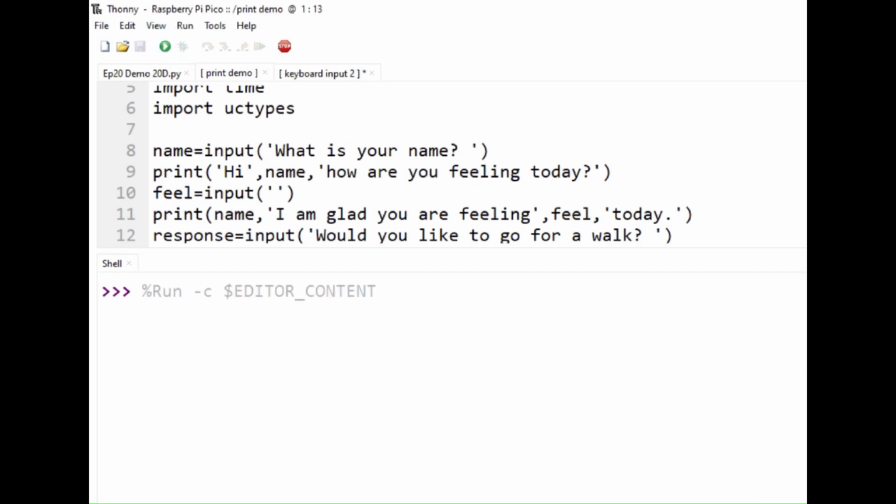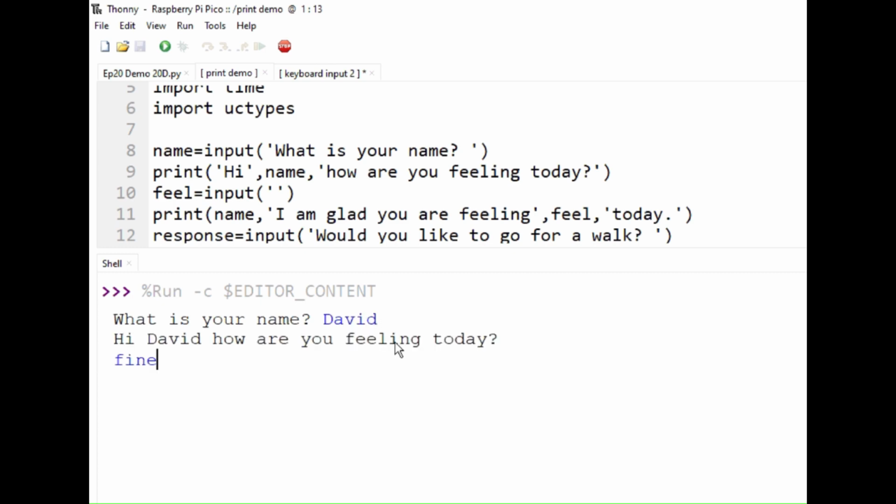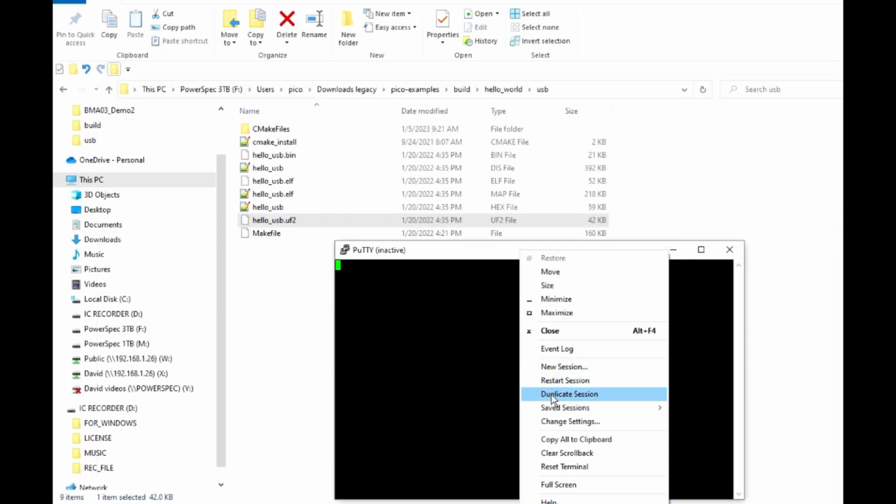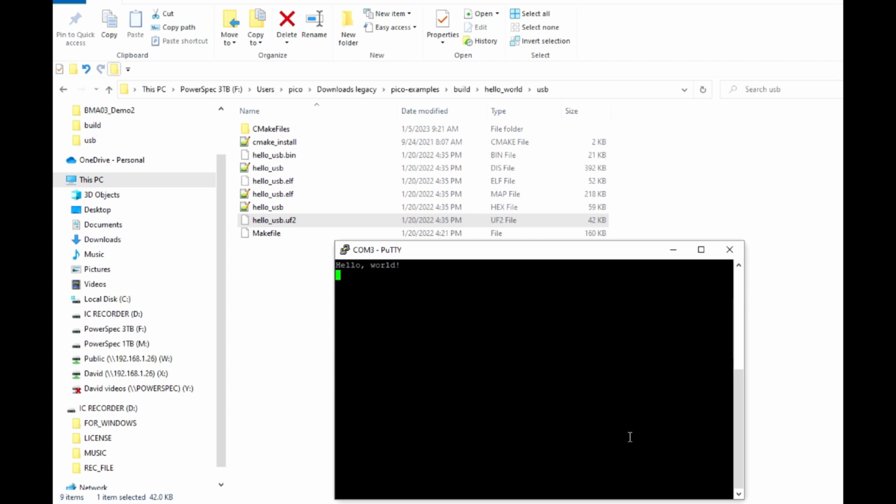Communicating between the Raspberry Pi Pico and the outside world is pretty easy when using MicroPython and Thonny. Using a print command with the appropriate formatting can yield fairly sophisticated output. Life is slightly more difficult when using C since a separate terminal is required. Usually a terminal emulator such as PuTTY and the USB port of the Pico are implemented.